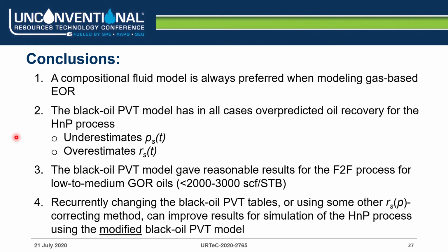And recurrently changing the black oil PVT tables or using some other method of correcting the Rs-versus-P over time can actually improve the results of using the black oil PVT model for simulating the Huff-n-Puff process. That is the modified black oil PVT model.